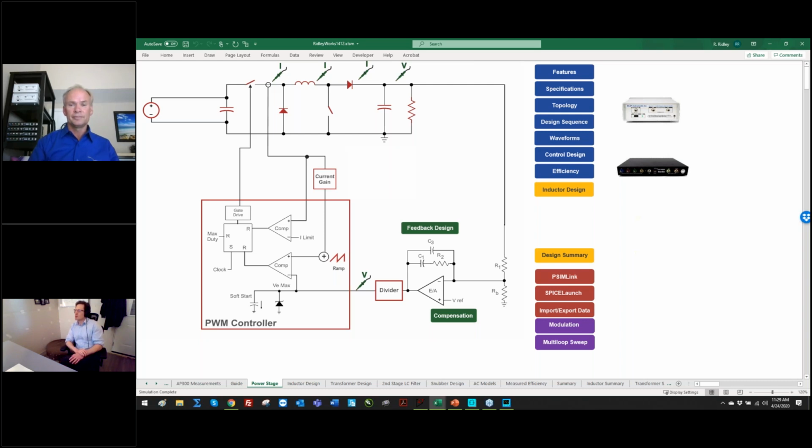A couple more questions about sweeping. A question: can we sweep an unstable circuit in open loop? In PSIM, the answer is no. There are 3 different methods of sweeping in PSIM. Our original sweep runs 60 cycles, and if a steady state hasn't been detected inside of 60 cycles, it will give up and move to the next frequency point.